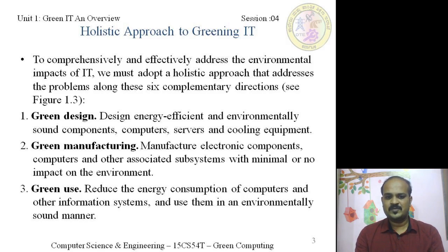Now most of the places are using LCD or LED monitors for computers. If I take the example of a 19-inch CRT monitor, it consumes around 80 watts of power. For the same 19-inch monitor, an LCD monitor consumes around 22 watts of power. And for that 19-inch monitor, an LED monitor consumes only 20 watts of power. So you can see the difference.